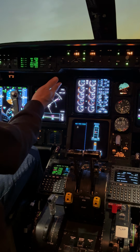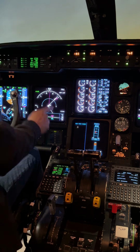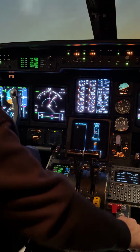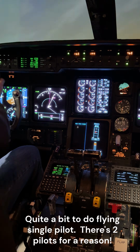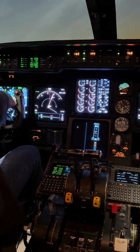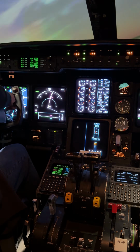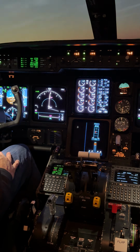All right, so we're turning on to final approach. You'll see the vertical glide path start to move in just a few moments. There's top of descent. I'm going to do 20 degrees of flaps. Flaps selected 20. Auto speeds will show 160. Vertical glide path is coming in, captured on our way down, and now our next altitude is 2,000 feet, and it says 2,000 here in blue. We're on the vertical glide path on our way down to 760.